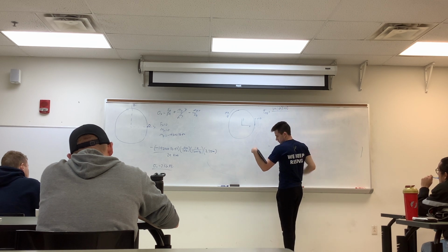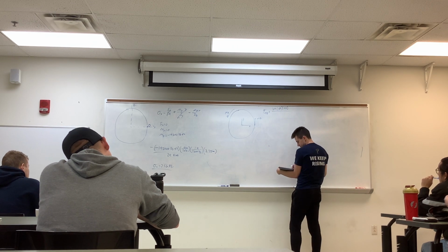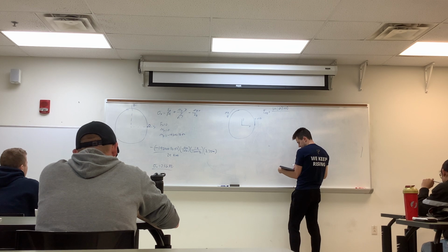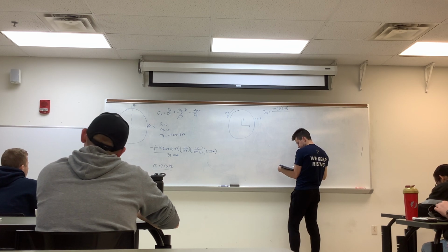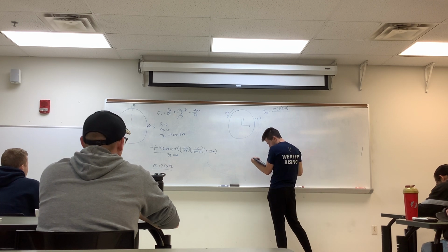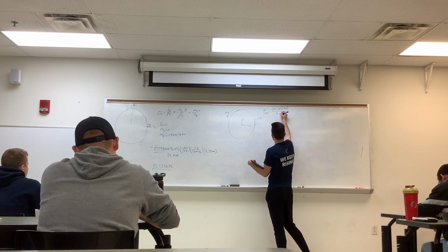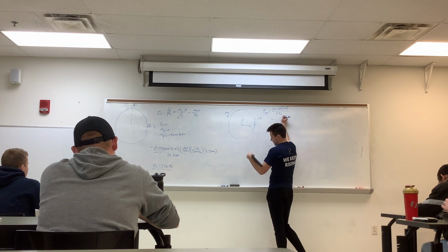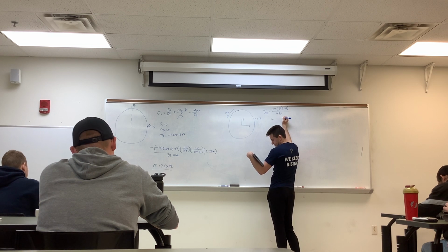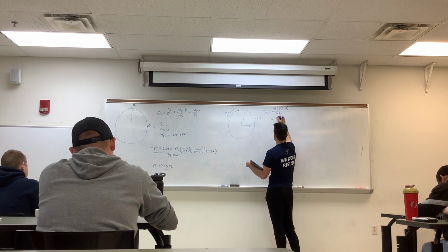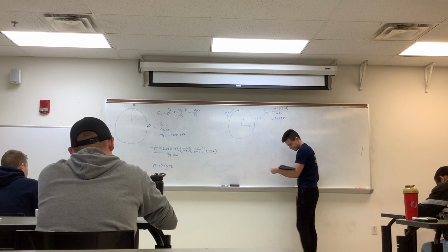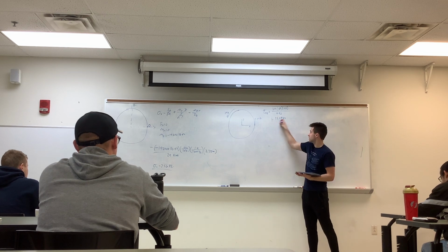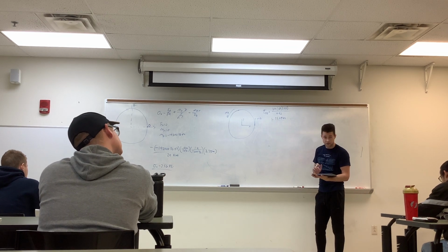All of that over J, which you can calculate for a hollow tube, happened to be about 49.6, giving this one to be 15.97 KSI. So that's with regard to our moment about x, or our torsional moment.